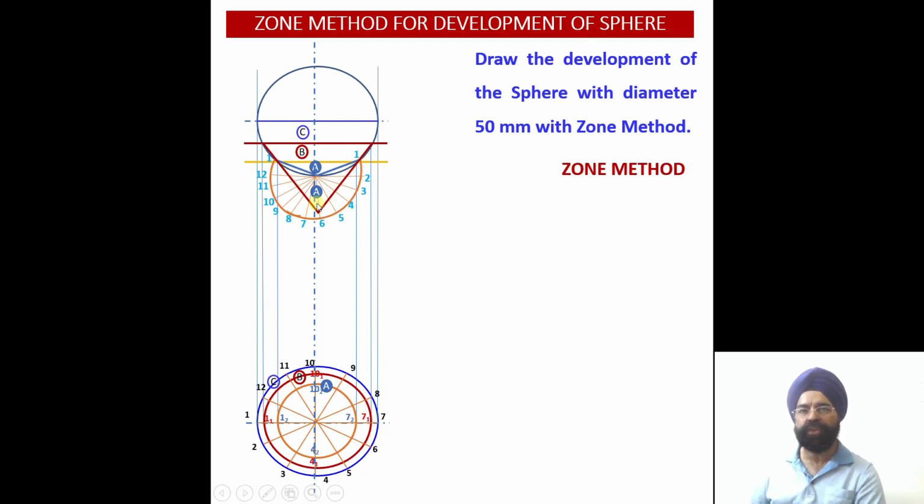So this gives me, you see, the slant edge of frustum of a cone, because I want to make only this development. The upper part development I have already made. Now my frustum of a cone is this one, you see, frustum of a cone for the second segment, right? So I want to make development of this, so I have extended this, I have extended this. So this is my frustum, and we very easily know what is frustum of my cone development. This is my true length of the slant edge. Why is this the true length of this slant edge?